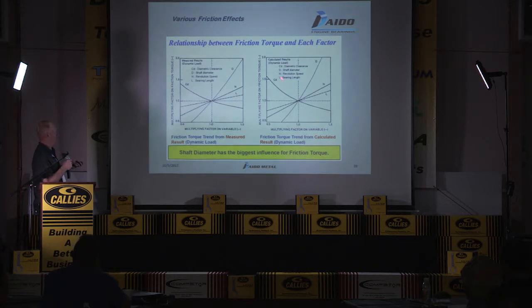This is important here with the clearance and the amount of friction. So you also have the amount of friction, basically the power it takes to spin that bearing or to spin the assembly, decreases with the increased clearance.